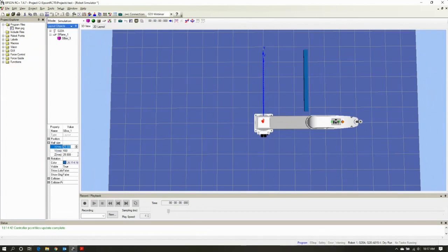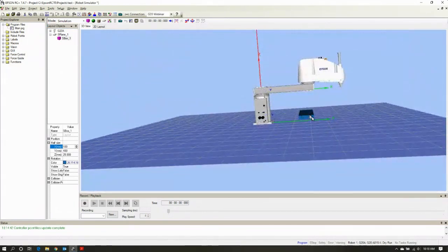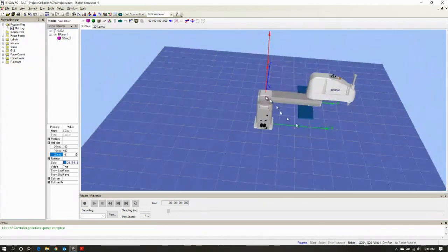Let's say though, I want this to be 200 millimeters wide. I put in 100 millimeters on my X, and I now have something that's 200 millimeters wide, 800 millimeters long. But as I rotate this, this might be the thickness I need with my drive rollers. If I want something thinner or thicker, I can then come into the Z. Let's say I'm running a thinner conveyor at this point. Maybe I just want 20 millimeters thick. And again, because I'm putting in half size from the central point to the edge, I can now thin the conveyor out.